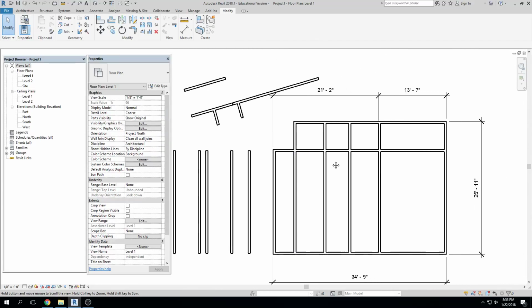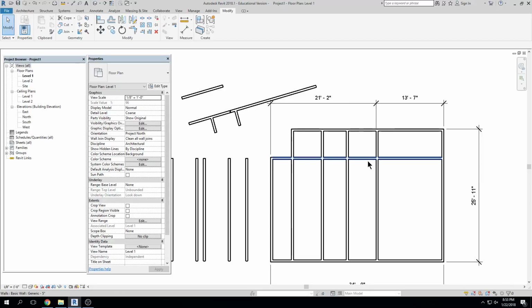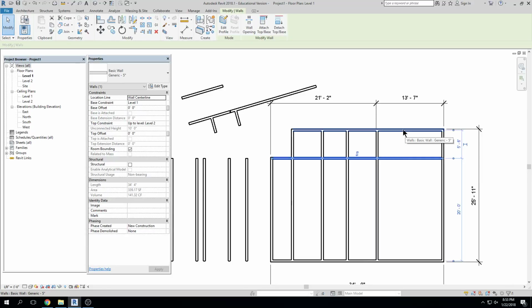So for example, if I want to take this wall and mirror it about this axis, when I use the mirror command, it will take this wall and make an exact copy along this axis, meaning there will be the same distance from here to the new object as there is from here to the old object, right? It creates a mirrored copy. And in a mirrored copy, mirrored distance.